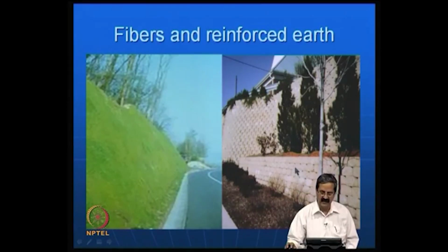So, this is another case of a reinforced earth wall. What you saw previously was a simple reinforced earth wall. This is actually a 2-tier retaining wall, where depending on the profile requirements, whatever profile you want, one can construct nice slopes. The facing elements here are what are called modular blocks. Then the native soil will be behind this.